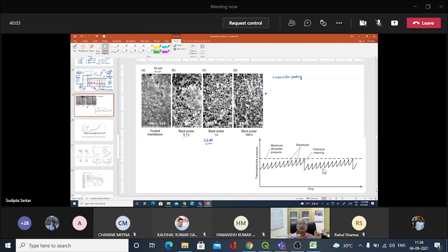So as you go on doing cycles after cycles, obviously the pressure drop across the membrane or cleaning membrane will increase. So please look at this diagram now. This is a history of a microfiltration membrane over time. You can see these ripples right here. This is the start, a clean membrane, or the new virgin membrane, this is here.